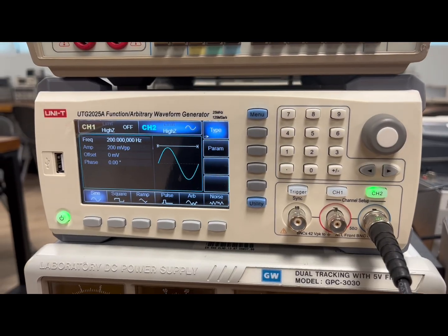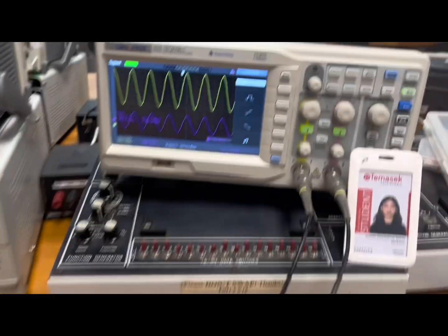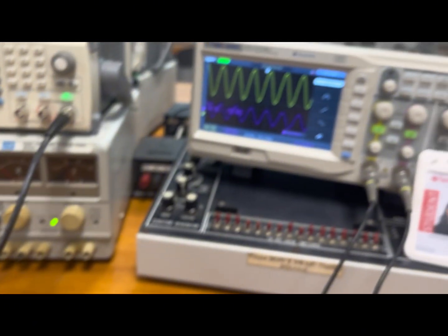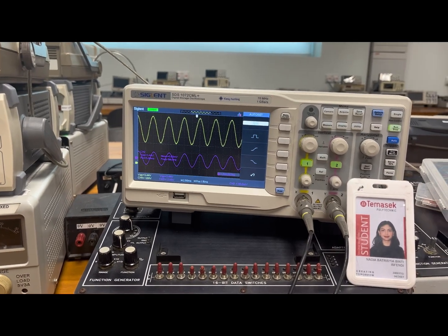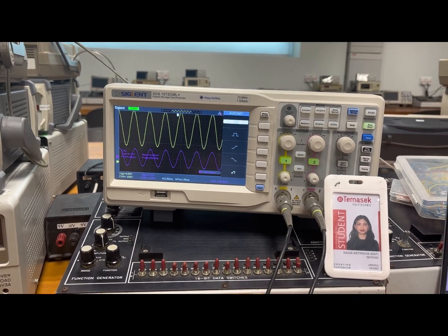Set the frequency to 200 Hz without altering anything else. Since the frequency is below 500 Hz, unity gain is applicable, hence the output voltage at TP3 and TP4 is about the same. Just like previously, the output waveform at TP4 will be determined by the output at TP3, hence by adjusting the trimmer at stage 2, it can also control the output at TP4.